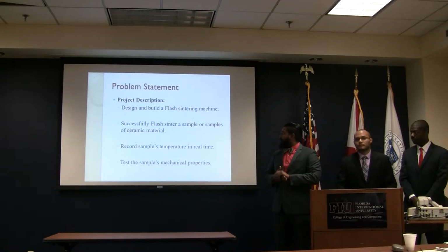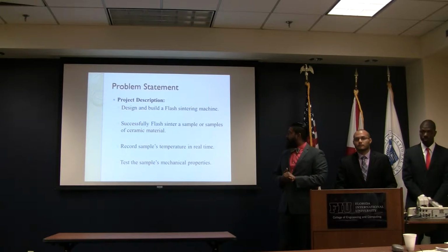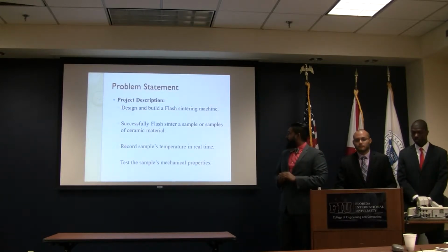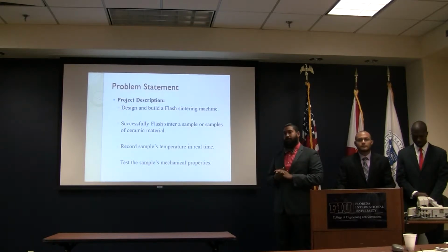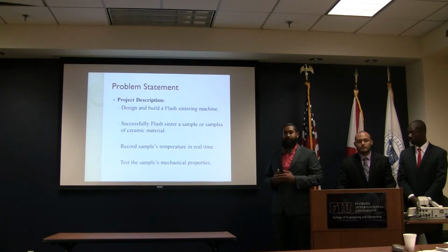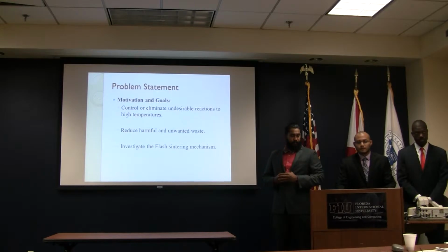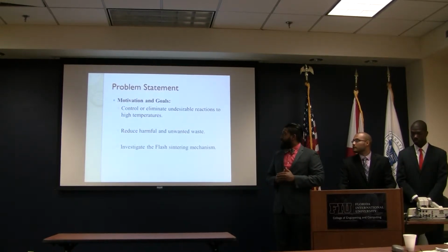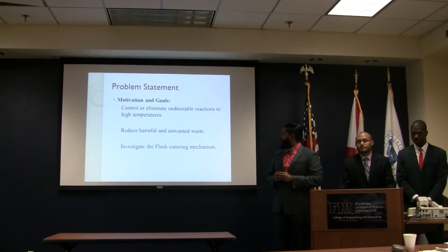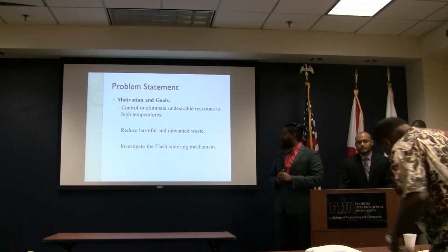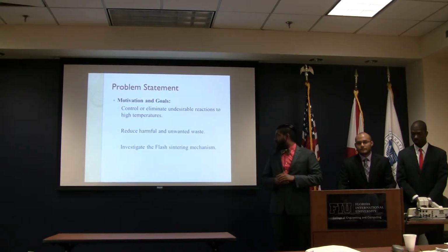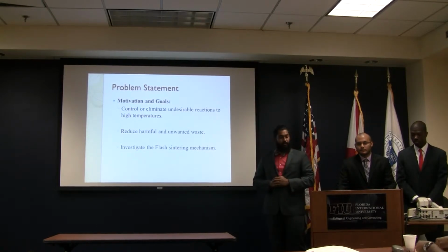For our problem, we want to build and design a flash sintering machine. We want to successfully sinter ceramic materials, and at the same time record that sample's temperature in real time, and then afterwards test the sample's mechanical properties. We hope to control undesired reactions to high temperatures, reduce harmful and unwanted waste, and investigate flash sintering mechanisms.